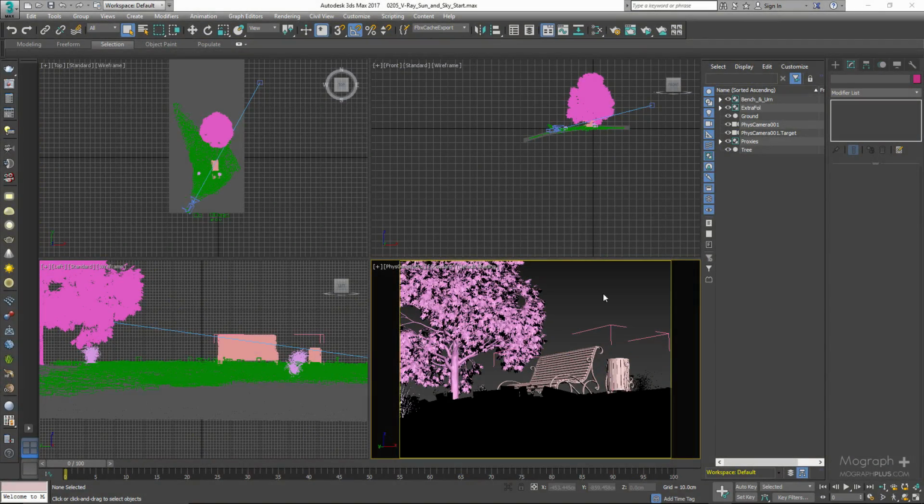In this lesson, we are going to talk about 3ds Max's light compatibility with V-Ray and basically how 3ds Max lights can be utilized in V-Ray. First of all, I wouldn't recommend using 3ds Max's lights with V-Ray even though they work, but always remember that V-Ray lights are optimized to work with V-Ray and almost all the time will give you better results. Let's start with 3ds Max's daylight system, which can easily work with V-Ray, and it offers some features that the V-Ray sun and sky system does not.